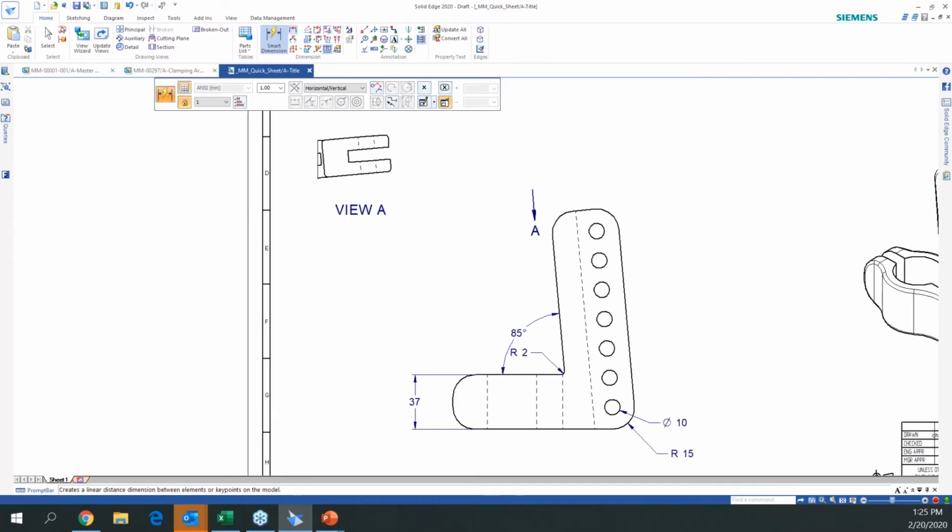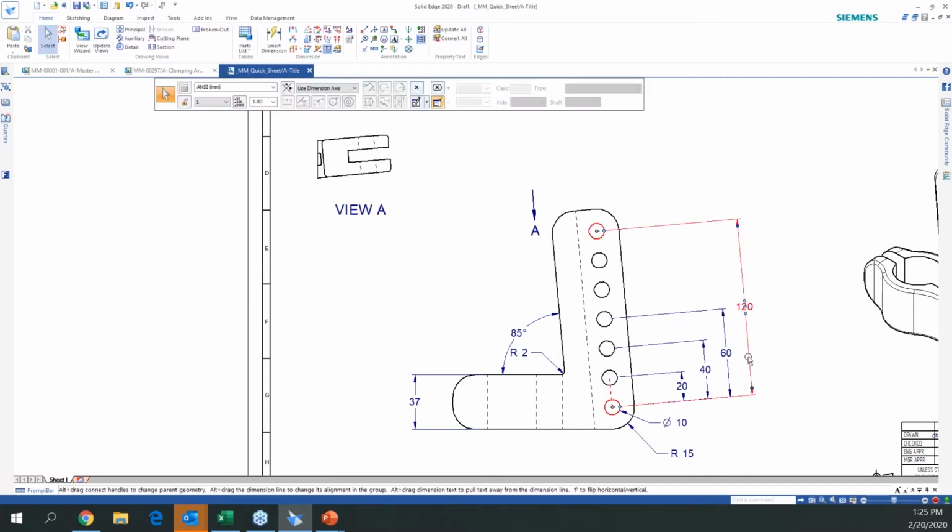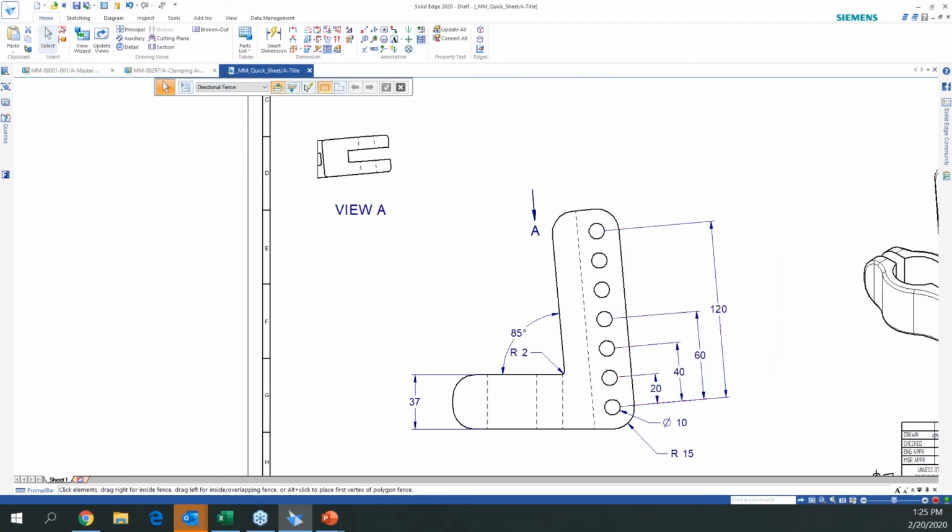Also, we can get in here to distance dimensioning. So if I pick the distance dimensioning between these 2 holes, there's the 20, okay? I could build onto this. So there's the dimensions from the first pick to the last pick, okay? And you can see they're all grouped together too. So if I exit out of there and if I take this one, highlight the 1, I can actually drag this out and keep that group together. So which is really nice.